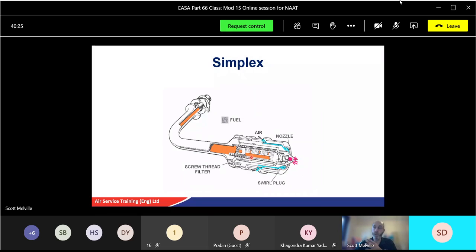Maybe a pipe's been disturbed in between the burner and the fuel pump for whatever reason, and maybe a little bit of debris got in there. The last thing you want is debris going out the nozzle. The nozzle is very, very small because it's got to make that spray to get the fuel into the combustion chamber. You also have air, a little tapping of air going in as well, and that helps mix up with the fuel, make a good recipe, and help spray it into the combustion chamber. And take a tapping from maybe the bypass or something like that as well, or even maybe the back of the compressor, sorry. And that comes out as a single point and then sprays into the combustion chamber under the correct conditions. And that's a simplex.